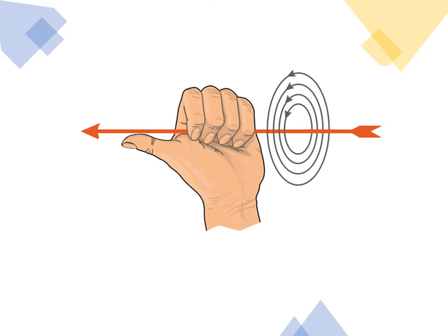But I will be using electron flow. So my example will use the left hand. You can think about the current-carrying conductor like an arrow, where you would grab the arrow in a fashion that your thumb would point in the direction that the arrow would fly.